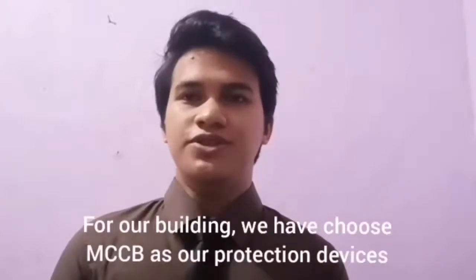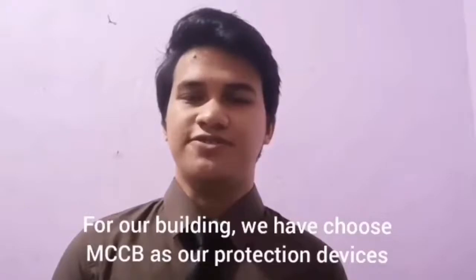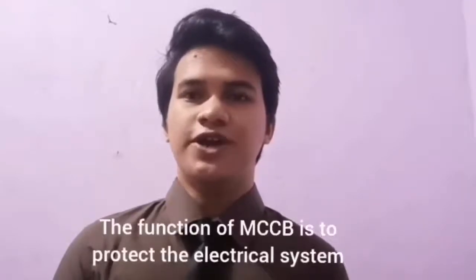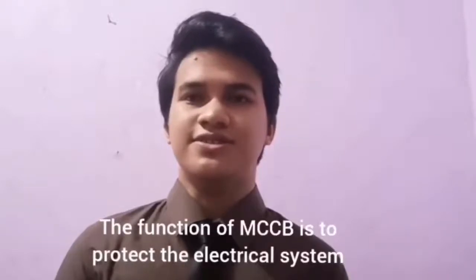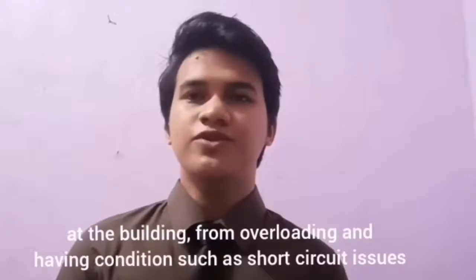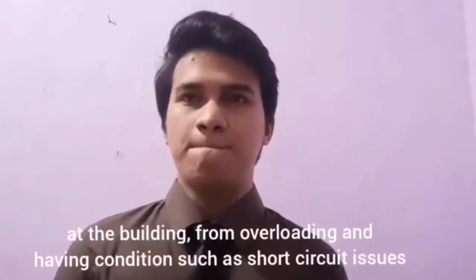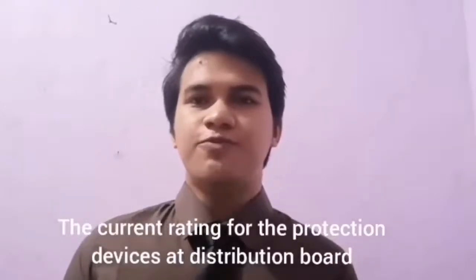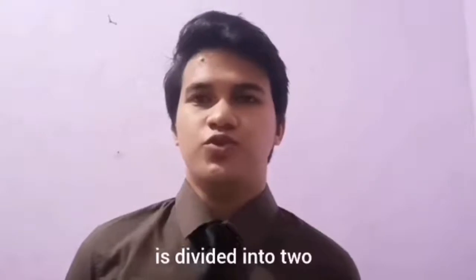For our building, we have chosen MCCB as our protection device. The function of MCCB is to protect all the electrical system at the building from overloading and conditions such as short circuit issue. The current rating for the protection device at the distribution board is divided into 2.